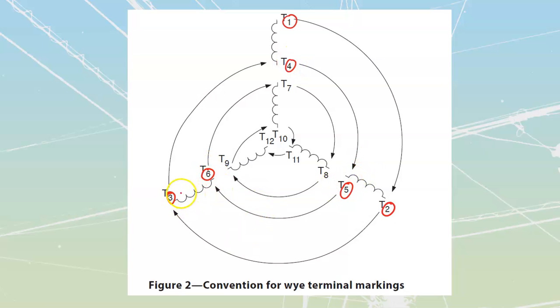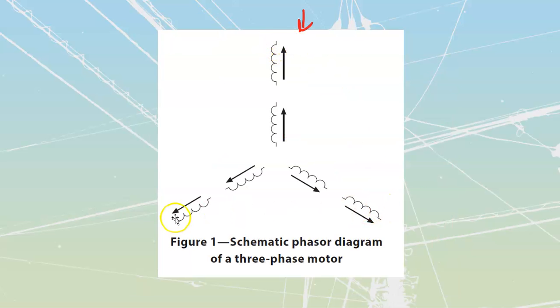So you should see that there is a connection out. 3 to 6 is a connection, 2 to 5 is a connection through there, 1 to 4 is a connection through there. These are connections that are made by the coils themselves. If I have more windings, I then move from the 4, 5, 6 to the next one in, which is going to be 7, 8, 9. And then from there, the next connection in is going to be 10, 11, and 12 going in. Just do it a couple of times over top of this one. Practice doing the 1, 2, 3, 4, 5, 6, 7, 8, 9, 10, 11, 12 to make sure you get those connections, because you will have to be able to make those on the fly at times.